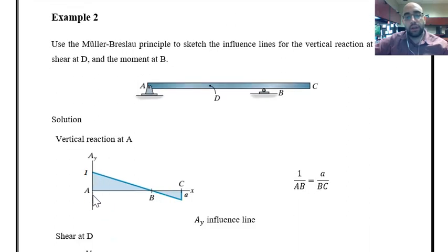That's what I have over here. I remove the shear restriction, or vertical restriction, at A, apply a unit displacement, and then the deformed shape that you will see will be the influence line for vertical reaction at A. This value over here is equal to 1 because that's based on the very basic definition of Muller Breslau's principle.